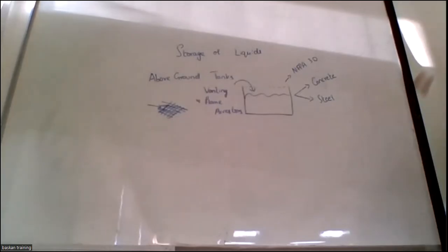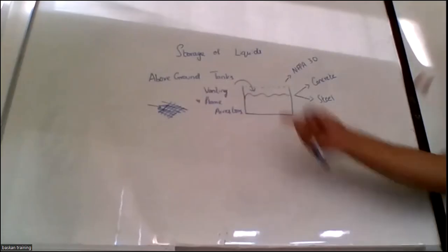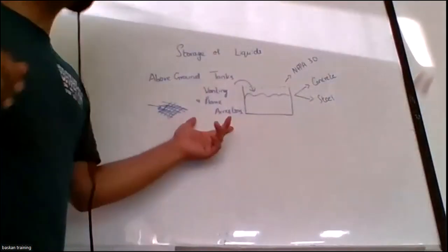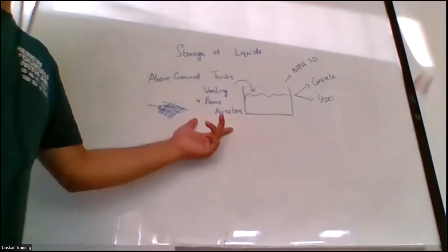If you'll see, remember we were discussing in section 17, high pressure gas, whenever it releases, static charges are accumulated and you need to ground all the nozzles. Similarly, you have to ground the tank. So static charges that are accumulated are grounded appropriately. So appropriate grounding should always be provided. So the first important component is having venting and flame arresters.